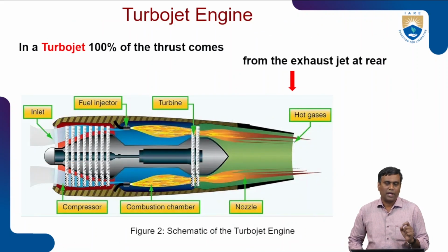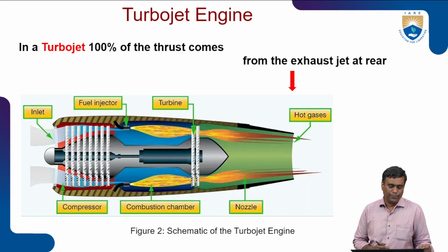This is just again to recap. This schematic of a turbojet engine. Basic components remain the same in all these 4 types of engines. That is the compressor, to compress the inlet air. Then it passes this compressed air to the combustors, where fuel will be injected. Combustion will take place, and then high pressure and high temperature exhaust will be passed through the turbines.